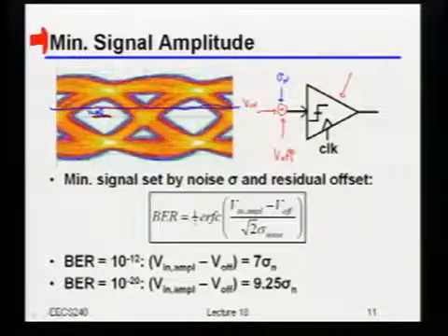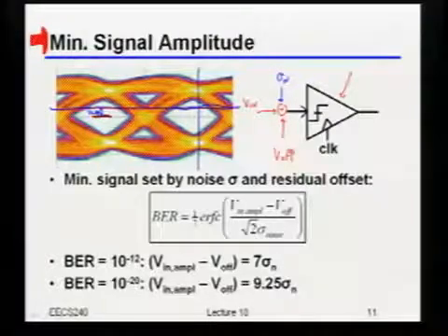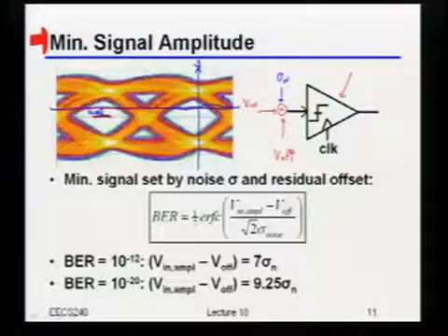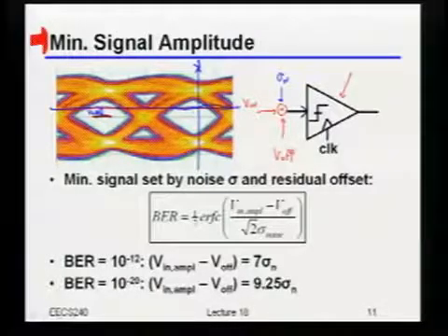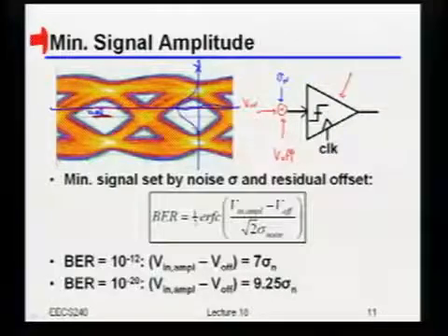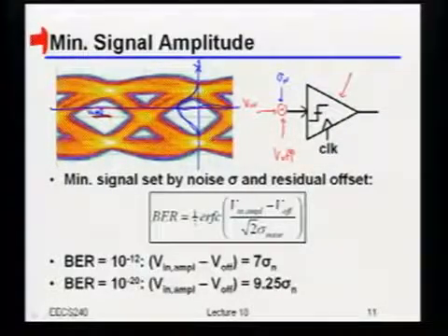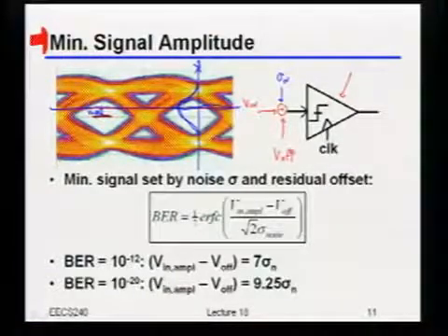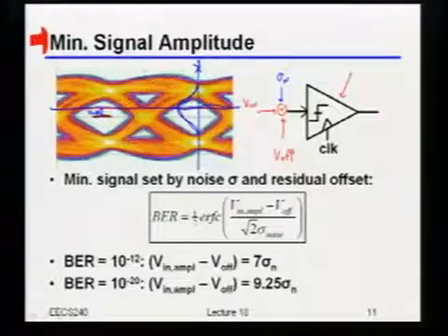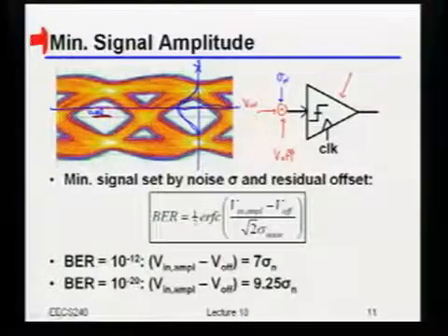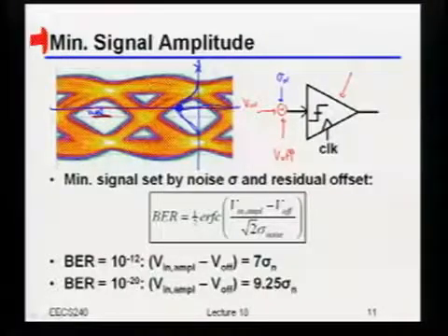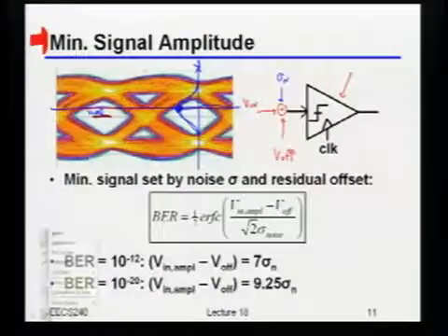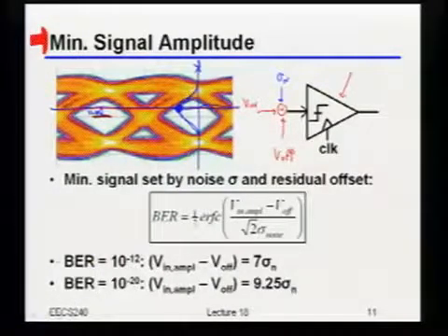So what I'm going to do now is draw this in a little bit funny of a way. I'm just going to draw a picture, and it's actually, I think, already on your slide, of how big that thermal noise will be versus the probability of actually getting that amount of noise. It's going to look something like that shape right there. Let's say it's a Gaussian. Something that's larger in the left direction means it's more probable. So obviously the mean should be 0, but I have some probability of getting things larger than that, obviously.